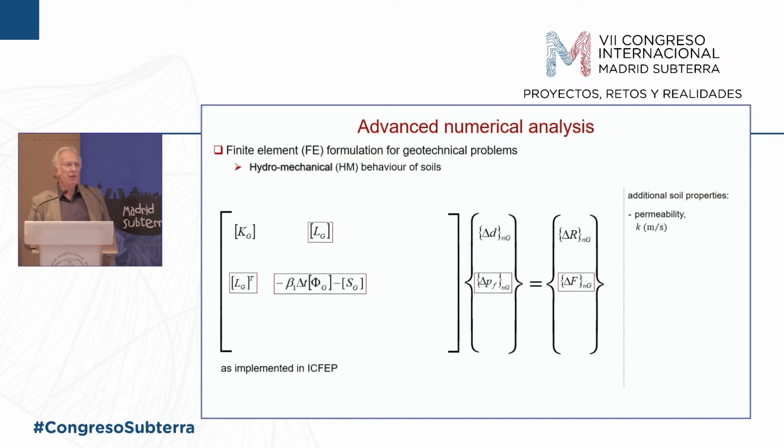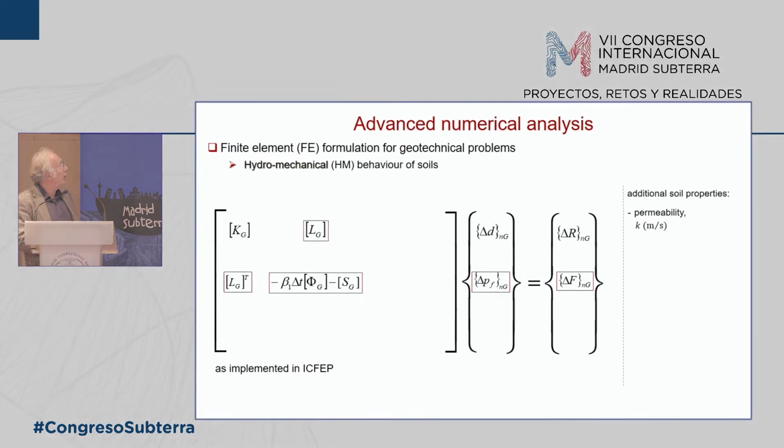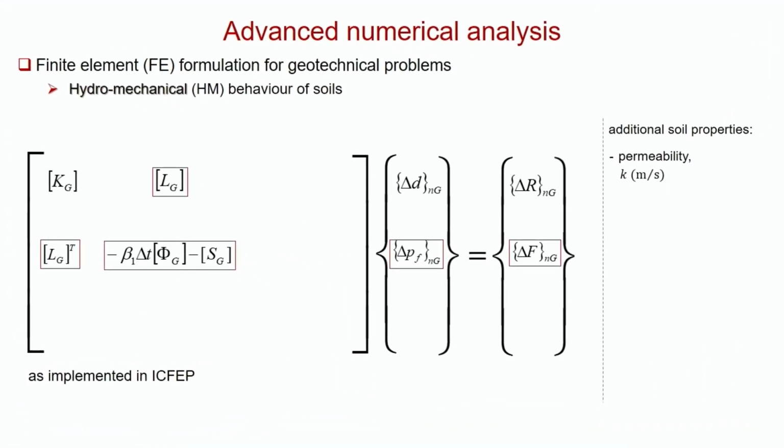If we want to deal with time, for example, and I'm going to show an example in a minute, if we want to say, well, what's going to happen after 6 years, or will my structure fall down before it gets to the long term, we need to advance our analysis and introduce seepage, the way excess pore pressures dissipate that are created when we load the soil initially.